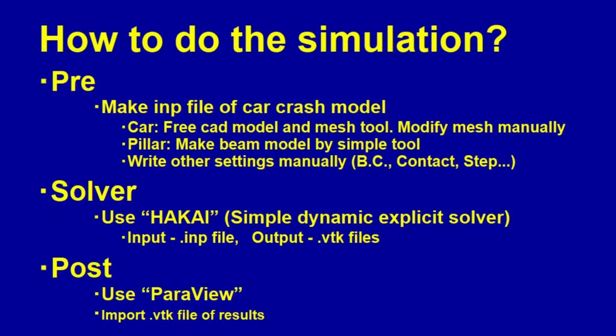First, I'll talk about how to do the simulation. For the solver, I use HAKAI, which is a simple FEM dynamic explicit solver. This is an open source program and we can get it from GitHub. HAKAI uses an Abaqus inp file as input and outputs results as VTK files.